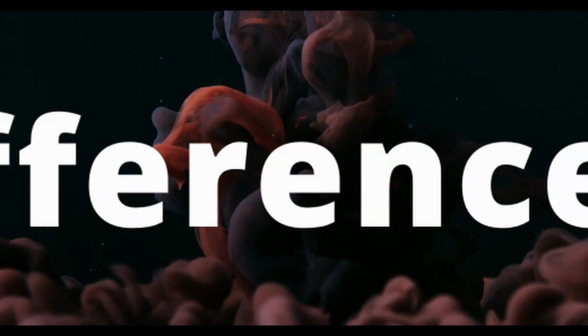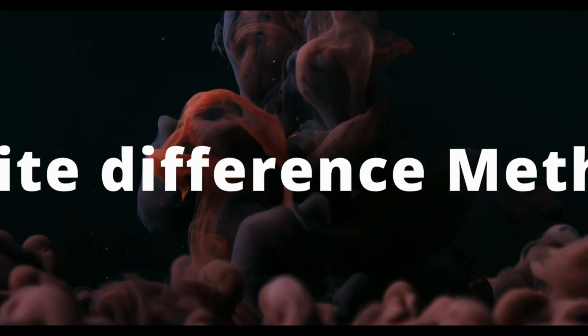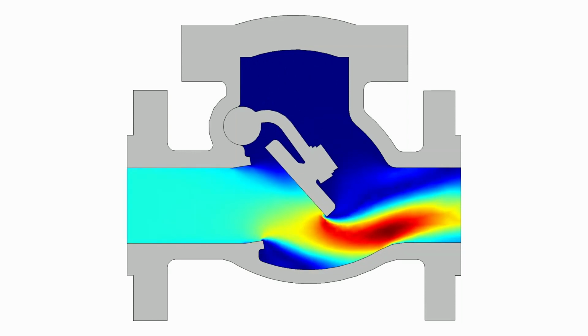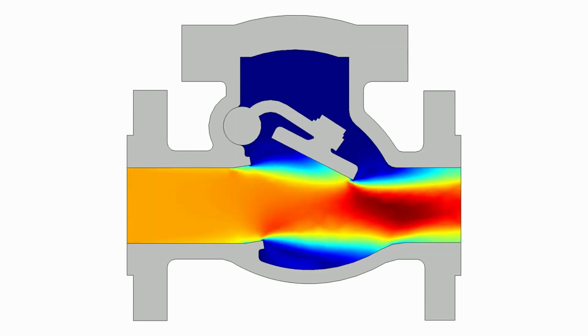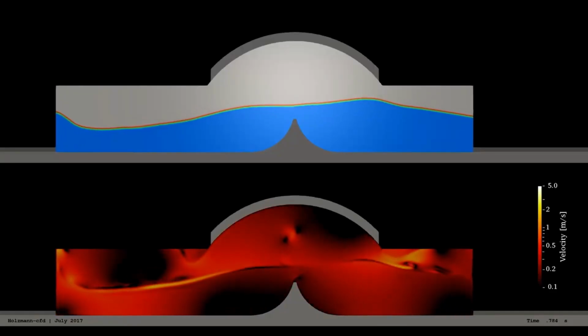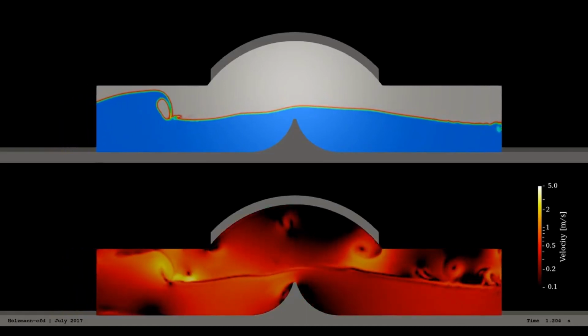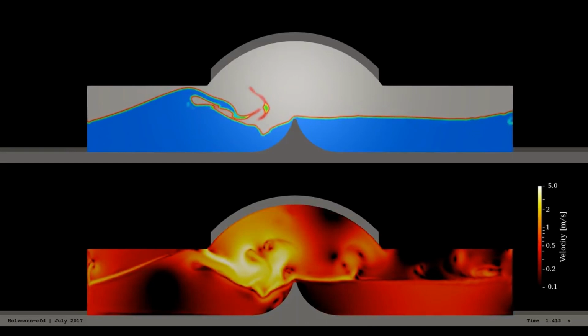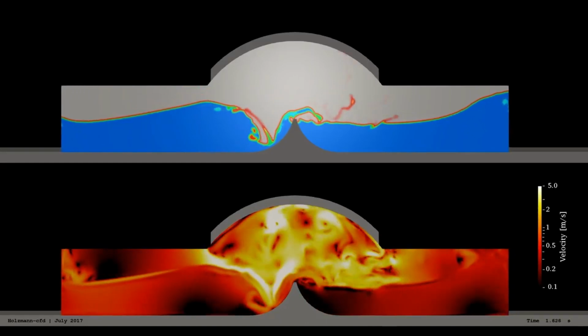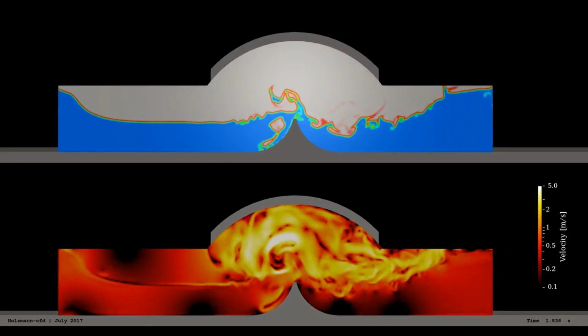Next is the finite difference method. The finite difference method discretizes the Navier-Stokes equations on a set of points that hold the physical variables of the fluid, for example pressure and velocity. These points are usually distributed regularly, as this makes things much easier for the implementation. To compute the derivative at a node, a Taylor expansion is utilized. Next is smoothed particle hydrodynamics.